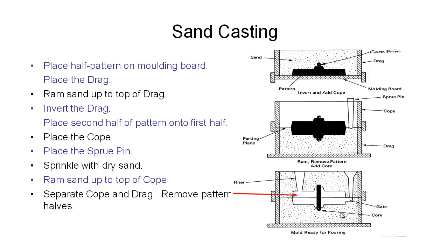The sand that they actually use for this type of molding is kind of like beach sand. It's got a little bit of moisture in it, so it kind of sticks together and you could build sandcastles from it. And they also put a few other additives like clay and sometimes a little bit of resin powder, so that it'll hold together when we're actually forming our sandcasting patterns. And then when the hot metal hits it, it'll actually form a nice hard shell, a barrier, to prevent the metal seeping into the rest of the sand and getting stuck in the part that we're making.